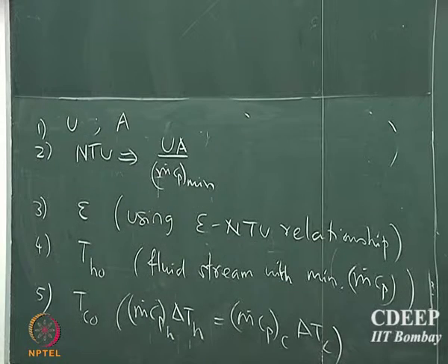Okay. So what we have suddenly found is a powerful method. Even if you don't know 2 of the 4 temperatures, you don't have to resort to the cumbersome delta T LMTD method. You can simply use the Epsilon-NTU method, which provides a nice and simple way to find out the temperatures. You can do vice versa. If you know one of these temperatures, you can do the reverse.